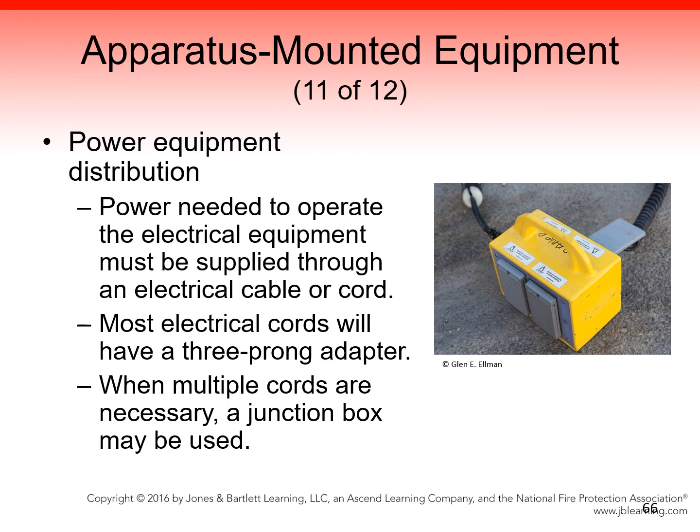A small light is attached to the top of the junction box to show that it has power and so the crew can locate it in the dark. This light turns on only when the junction box is charged with electricity. The junction box must be waterproof and durable, and have flip-up covers lined with soft neoprene rubber attached to the outlet openings.